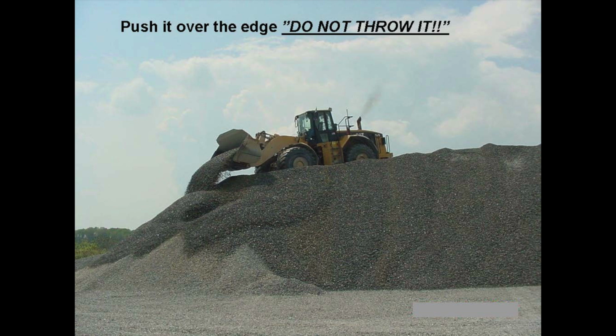This is like that stacker. You're throwing it off the end of the pile, what are you doing? You're creating segregation, right? You're giving that rock a ride. The coarse stuff's heavier, it's going to fly to the outside and roll down the hill, and the fines are going to stay closer in. So good intentions to mix that stuff up, right? Push your piles, keep them going. But there's a right way and a wrong way to do that, and we've got to make sure our loader operators are doing it the right way.